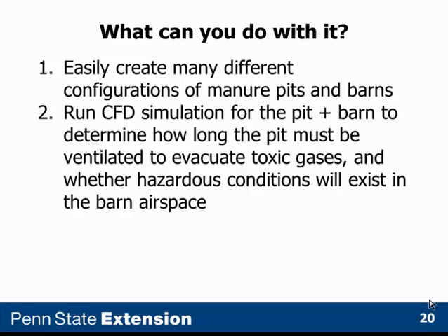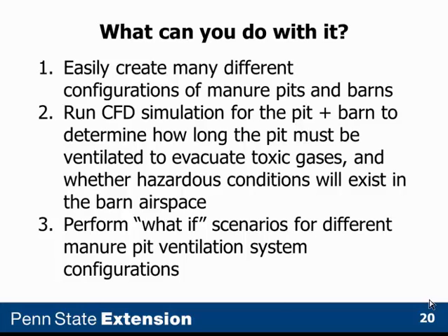So the tool is very powerful. And most importantly, for a given barn and pit situation, it allows you to perform a series of what-if scenarios for different manure pit ventilation system configurations. You, for example, might be interested in knowing what is the best way to ventilate this manure pit to evacuate the pit most quickly? Or how can I configure the ventilation system to minimize the portion of the barn above the pit that is contaminated during manure pit ventilation?